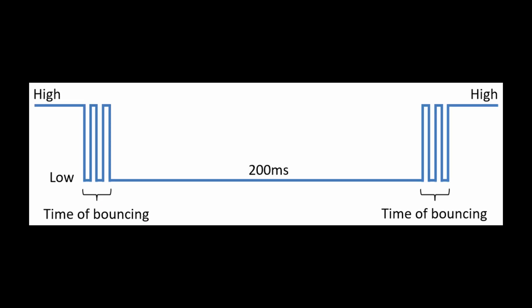Okay, so what do we need to do when a button is pressed and triggers an interrupt? Let's take a closer look at this process in this illustration. As soon as the button is pressed, there is at least one falling edge that triggers one or more interrupts. In this example, 3 interrupts would be triggered before the button assumes a stable state after the bounce time.